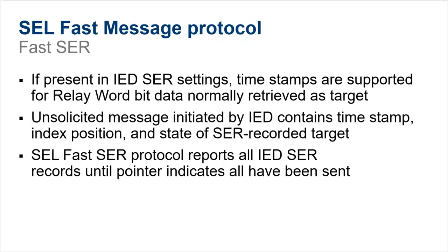SER is the sequential event recorder, and this can be used to create a list of data that you're interested in, an order of operations when things happened. And this data is then transferred over SEL Fast SER protocol.